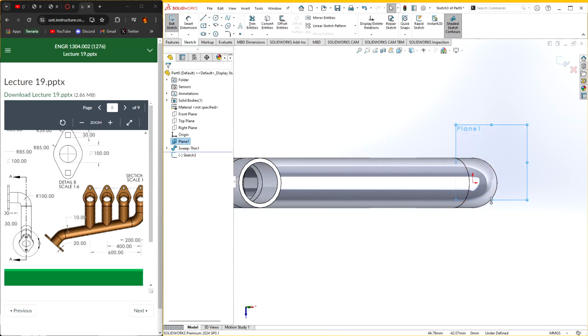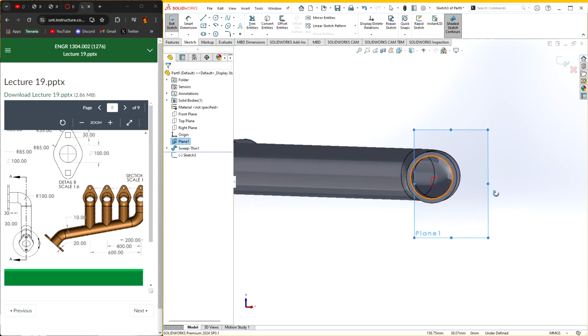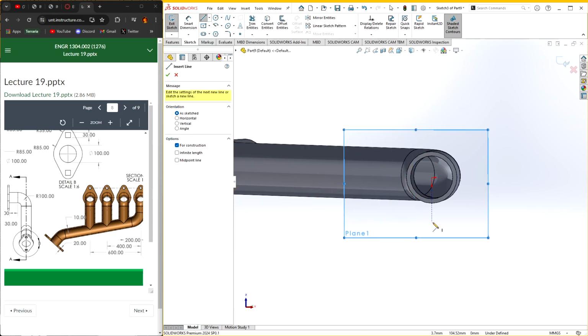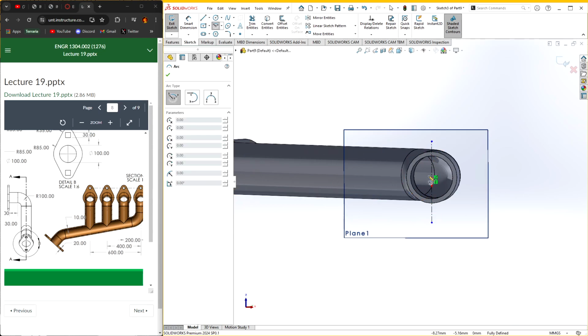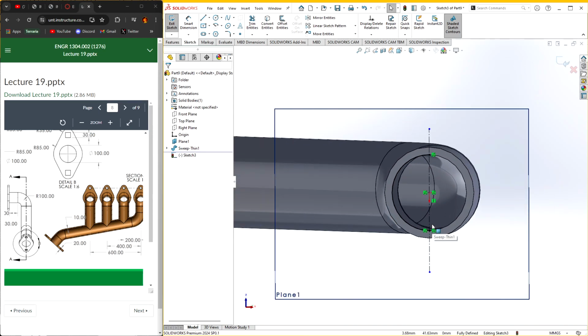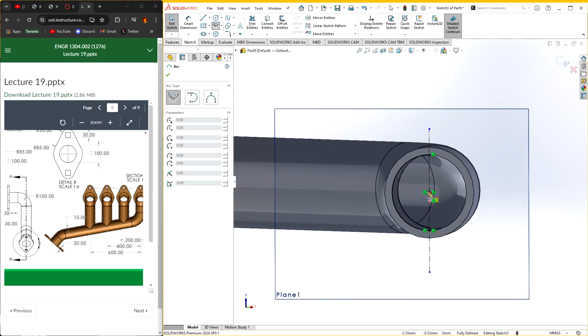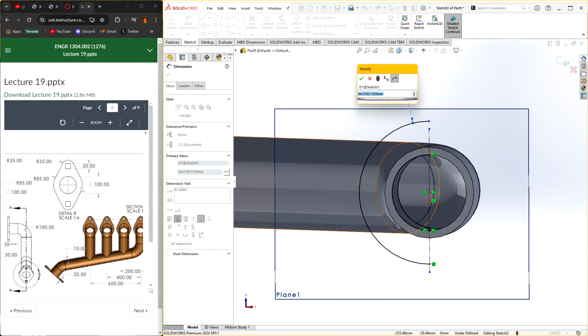I kind of want a bottom view on this, so let me go Control 6, and then move this up a little bit. That works. Let's do a center line from right here, where the origin is, and let's do a center point arc from the inner circle, just all the way around, just like that. Yeah, just like this. And then I'm just going to make another circle from here that goes out, just like that. Have this have a radius of, I believe, 85.